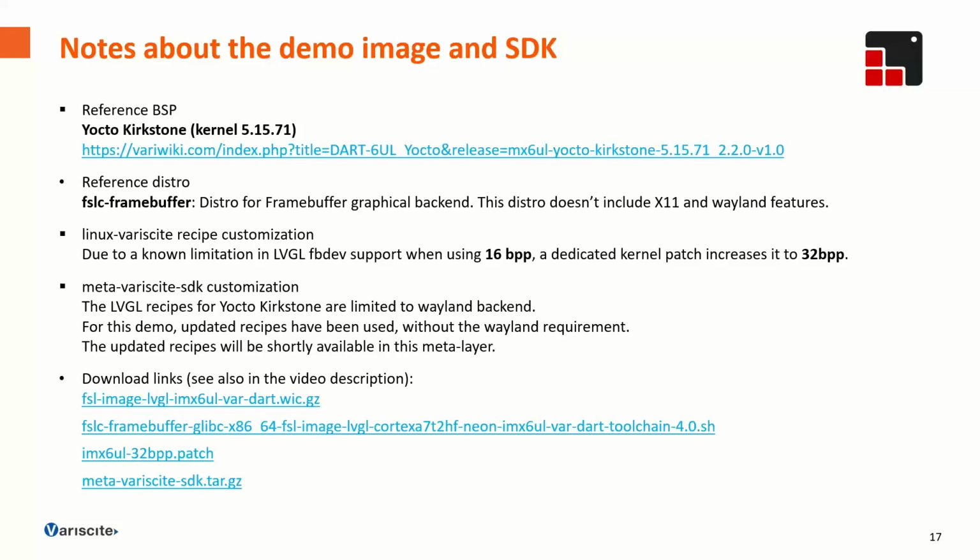Now, unfortunately, there is an LVGL limitation. There is a little bug when using this display version. So for this specific implementation, we switched the display of the 6UL to 32 bits per pixel, because this is the one that is actually working LVGL side.